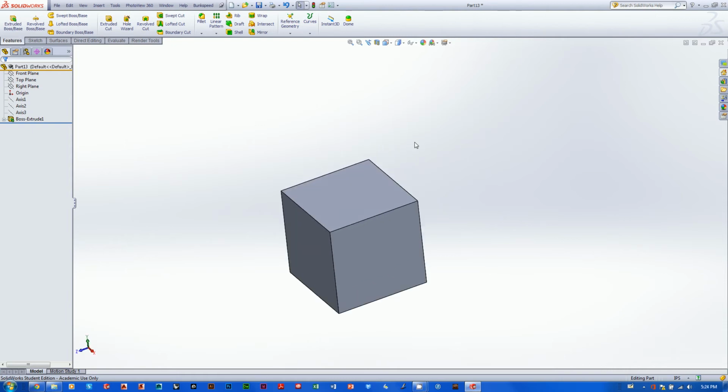This time I'm going to think to myself, how did I create this solid body? I know I started with a sketch, and here's the sketch right here, and then I applied this boss extrude feature. Well, the boss extrude feature is the thing that created not only the faces, but also the body. That's the thing that holds all of this solid piece. So that's what I should be clicking on, not just the individual faces.